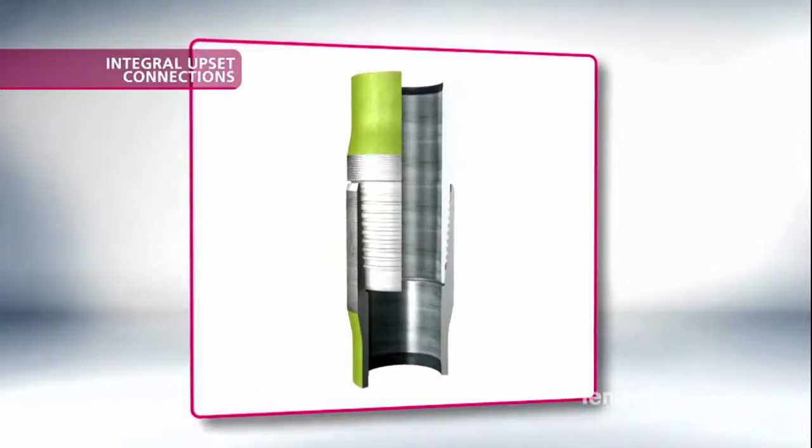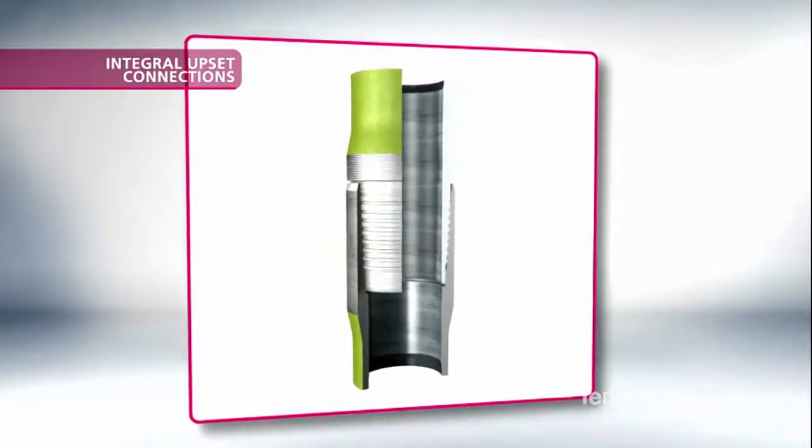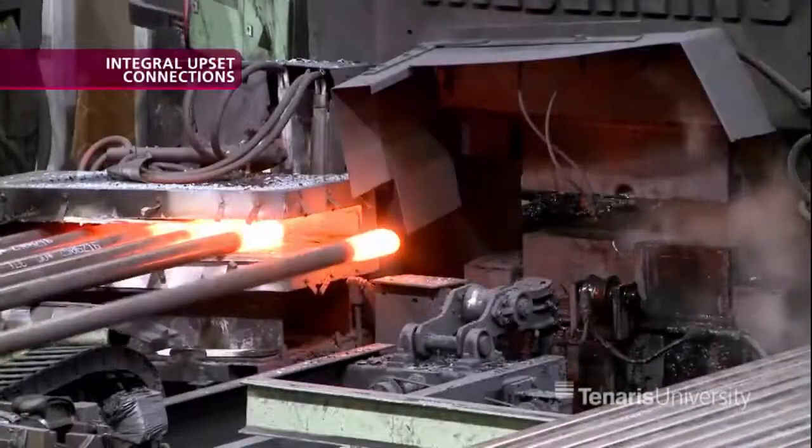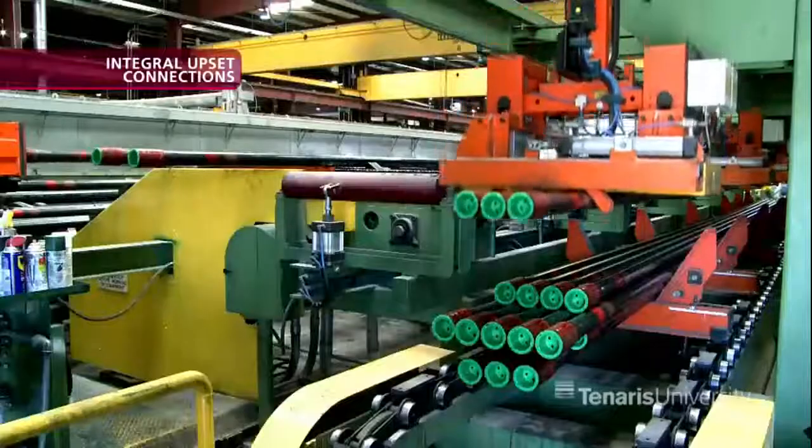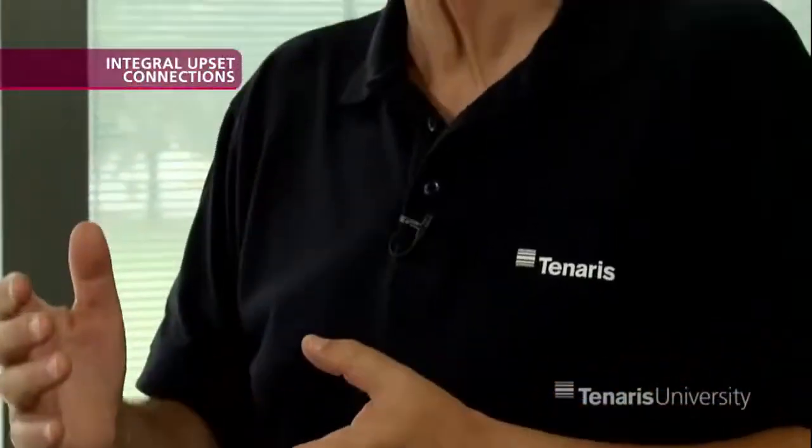These connections are threaded on pipes with ends that have been subjected to a process called upset. This process involves heating the ends of the pipes and pressing them in order to increase their wall thickness. The thickness increase results in a stronger thread geometry. Upset integral connections are especially suitable for downhole operations such as rotating and drilling a plug of cement, or running and pulling out strings several times in a stimulation or fracturing operation. This application is known as work string tubing.